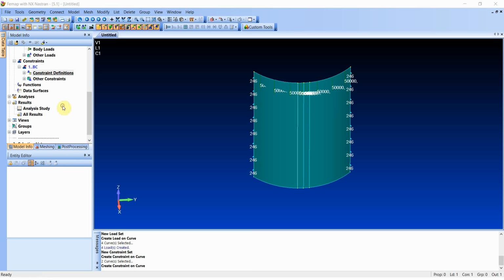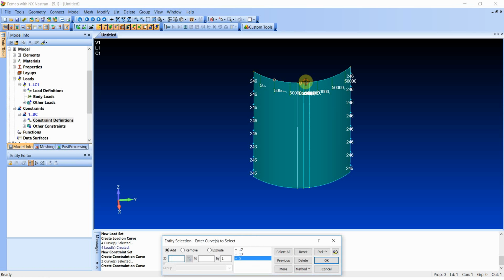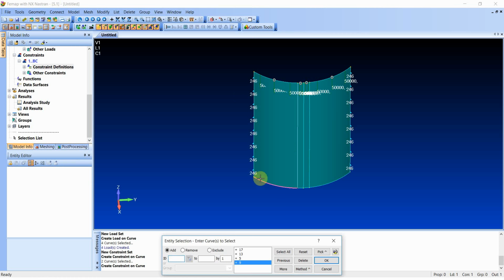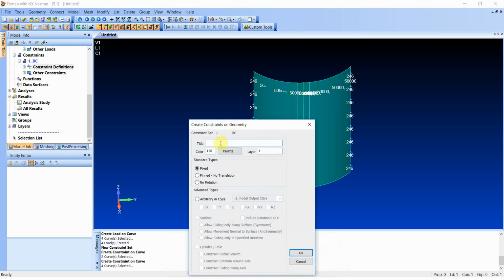I want to have a support that prohibits radial movement on top and on bottom, but I only marked top lines. I will mark bottom ones later on to create a secondary set, because I like to have things separated. I can name this top, and then after a while, when I get back to this model, or I simply wish to see what is happening, I have a clear division between what is constrained where. It is easier to follow.